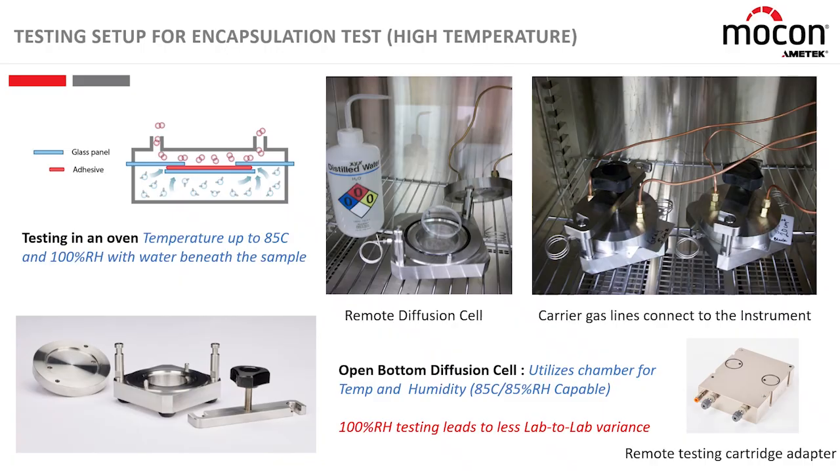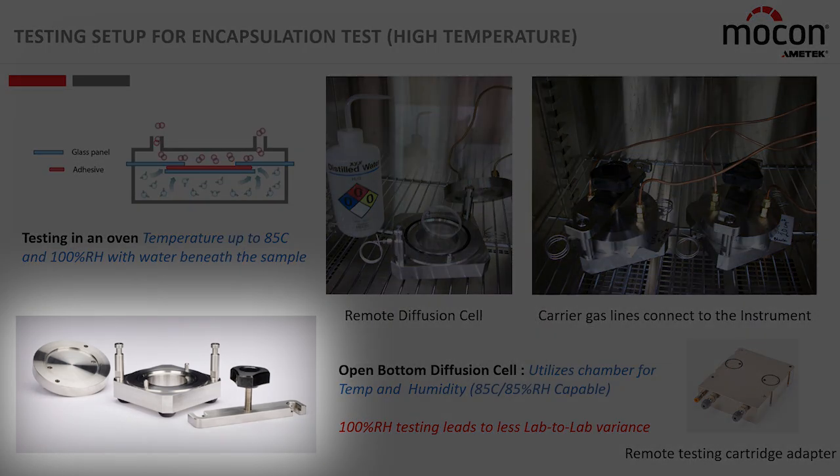We're not going to stress the sample, crack the sample. The system is going to still be at an equilibrium atmospheric pressure, but it allows it to vent, so I can still challenge 100% RH underneath. And with liquid water in here, it's not going to go anywhere overnight. It's going to last for a good long hundreds of hours of testing, which works out really nice. I do get asked by people like, couldn't you do 85C with 85% RH instead of 100% RH? The answer is yes, you can.